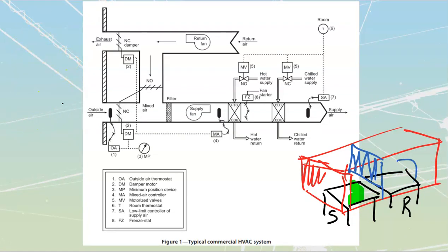Erase all that, give yourself some room. Okay, they start with our mixed air controller. This one over here. Because this is going to sense what my air temperature is, and based upon that air temperature, then we are going to adjust, right? We're going to make some of these adjustments to anything that is going to be our air that goes out into the supply. Supply air is always going into the living area. Return air is always coming back out of this one.